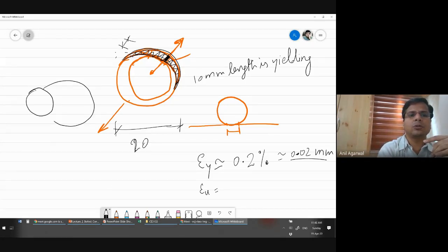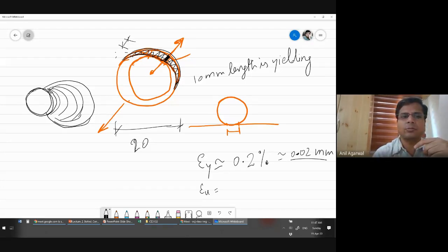This is the bolt hole, and the stresses right in this area are very high, but as you move away the stresses become lower. These are the stress contours I'm plotting. Only in the very immediate neighborhood would you have high stresses.